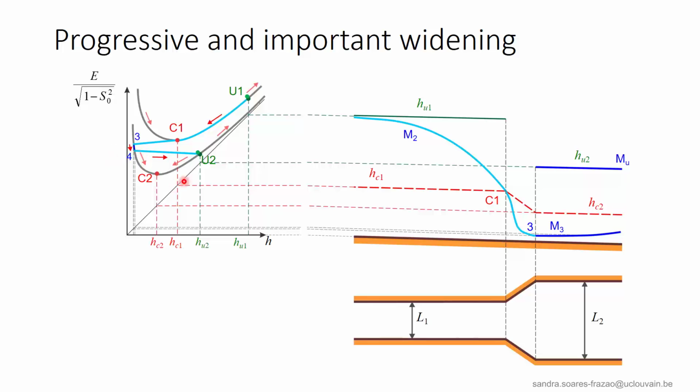We know that we have a uniform flow at the downstream end. So this implies a MU profile in the downstream reach, because, remember, no mild flow profile tends to the normal depth in the downstream direction. We calculate the sequent curve M3' and find point 4 as the location where M3' intersects MU. This indicates the position of the hydraulic jump.